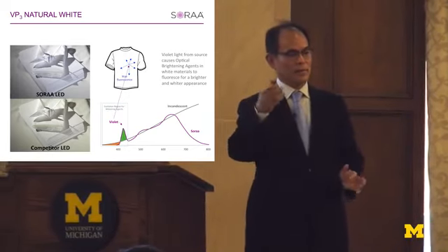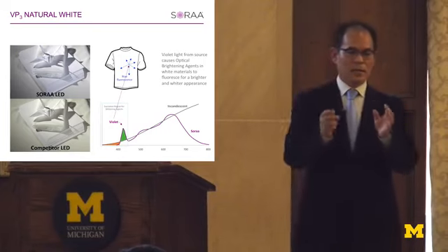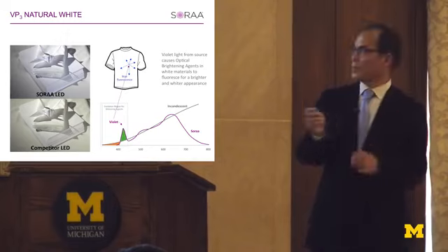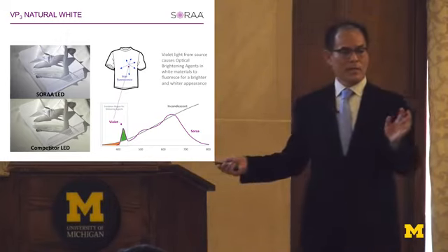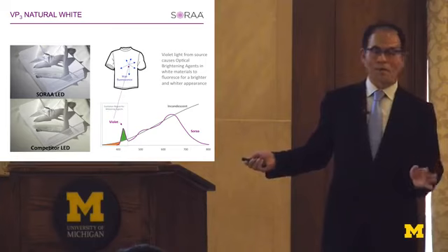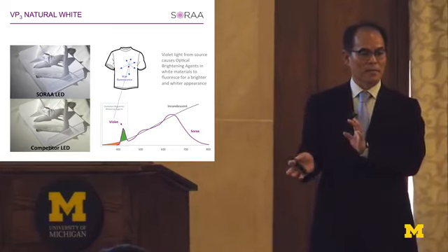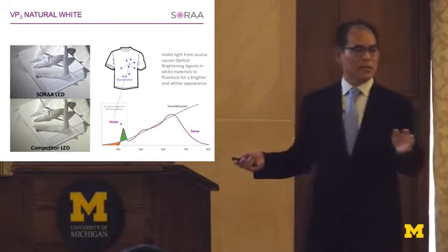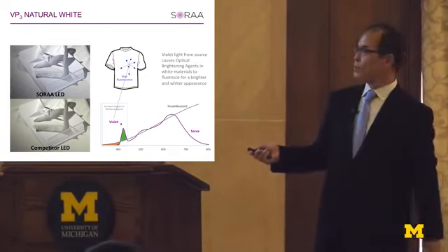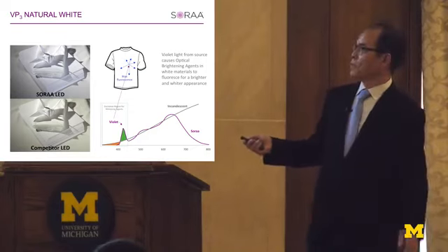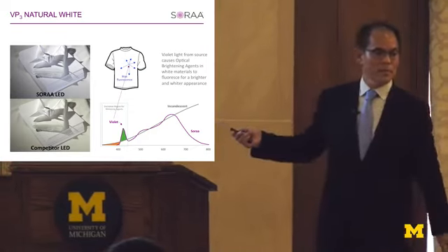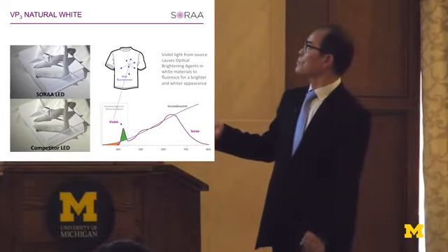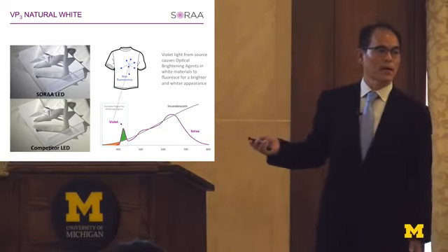My friend, one girl, tested it. The real color of the cosmetic under sunlight is pink. But under these white LEDs, it became yellow. Totally different color. White shirts you wash many times, no change. Always under white LED made by blue, yellow color. You have to wash many times. But under sunlight or solar lamp, white is white. Solar includes the violet, so violet excites the brightening agent, so white is white.